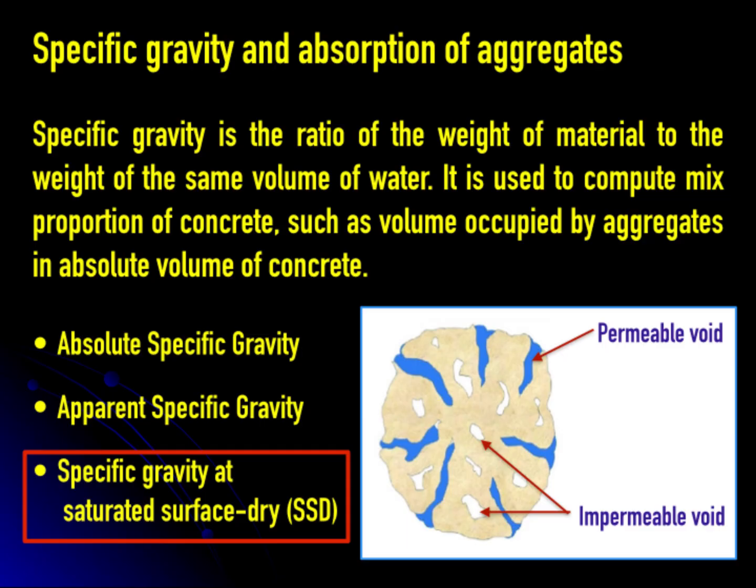Saturated surface dry, or called SSD, means the aggregate does not absorb or contribute water in the concrete mixture. I give you an example. Today is raining. The aggregate is in wet condition. Next day, the weather is very hot and dry. The aggregate is in dry condition.